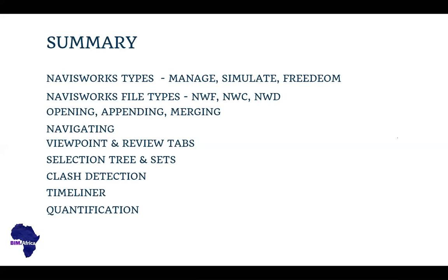Like I said during the presentation, at the beginning of every BIM project, there needs to be a document called the BIM execution plan. This document highlights all of the requirements, even before any design, even before a model. In fact, before the software is picked for Revit, a BIM execution plan needs to be done.